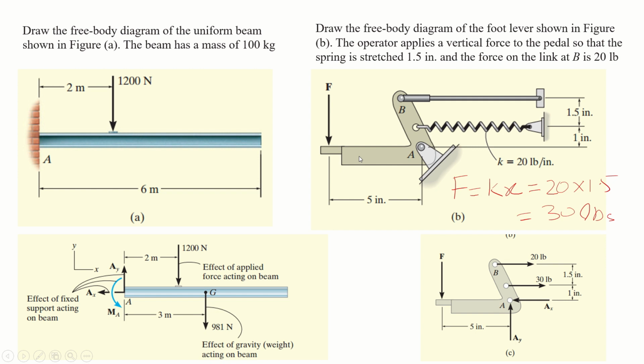So this is how we draw a free body diagram, in which the process is to first isolate the body from the surroundings and draw its free sketch. Then we will apply the action forces, and then we will draw the reaction forces.